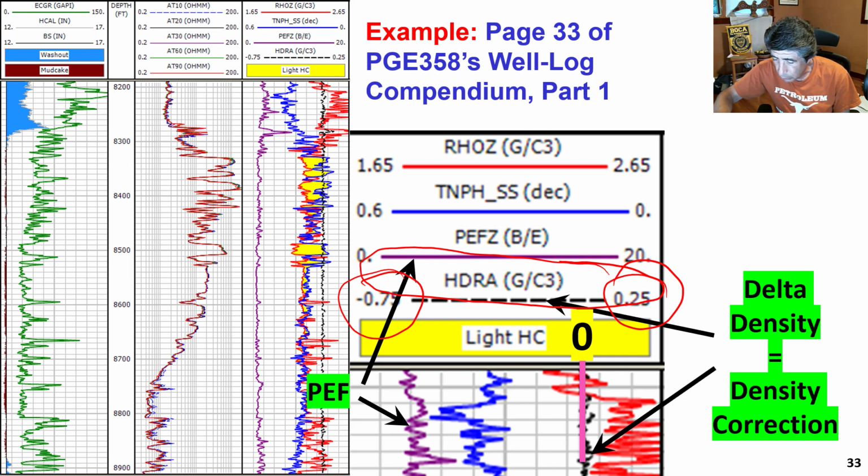But in essence, what we want to verify is that the correction is zero. That means that there was no correction made to the density measurement. If we see that some of these corrections are oscillating wildly in the left or right direction with respect to the zero, then we have to worry about it. This constitutes essentially another quality control log that is widely used to assess the reliability of the density measurements. So it's important to know how much of a correction was done to your measurements because of the mud cake, and that is reported here. Good.